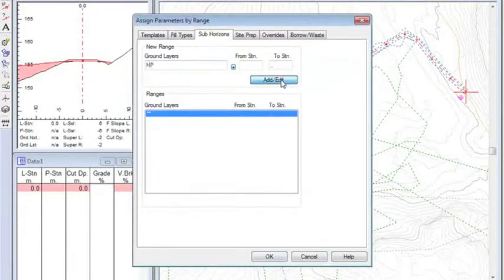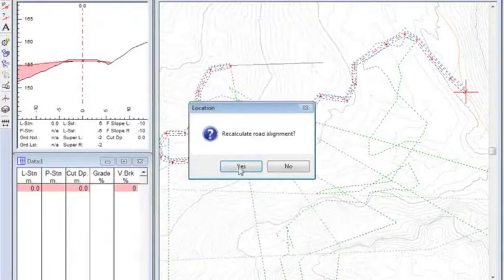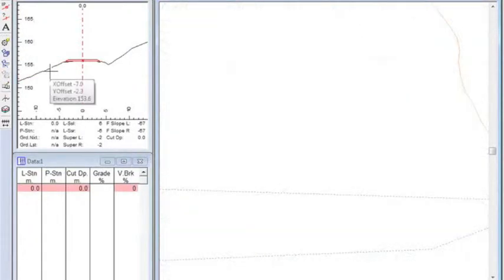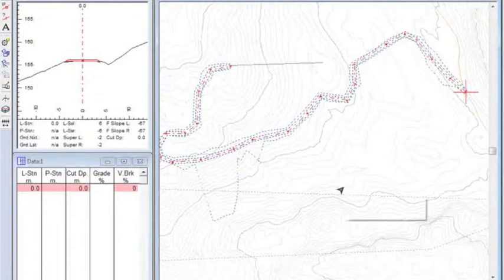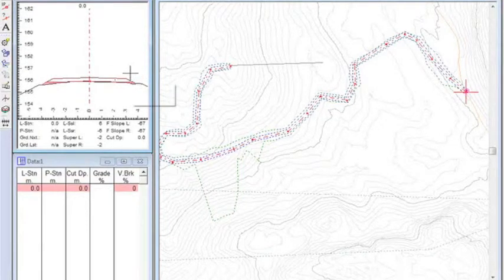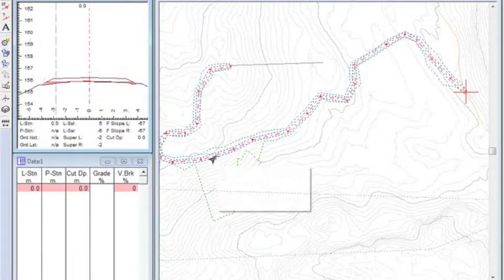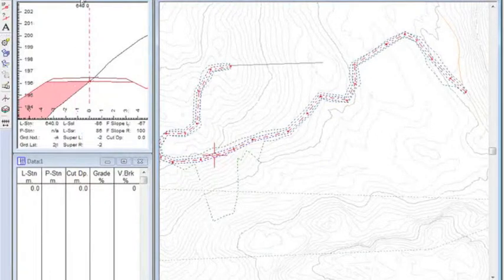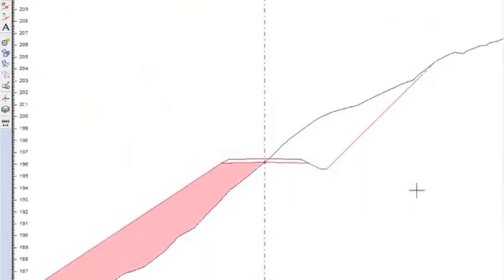Right, so I'm applying hardpan, add, edit everywhere, and immediately my cross-section will sort itself out because now I have a reasonable material in the ground. And is everything else okay about that cross-section? It looks okay. It's about 3 meters wide each side, or 6 meters total. It's got some crown on it, and seems reasonable for a forest road. Immediately looking at this, I now see an issue here. Looks like that should be full bench cut. This is where we've got our steep side hill.